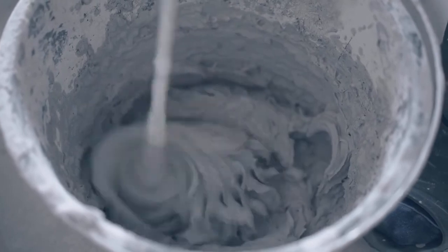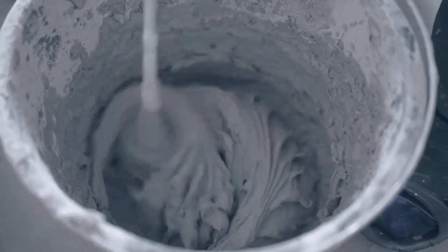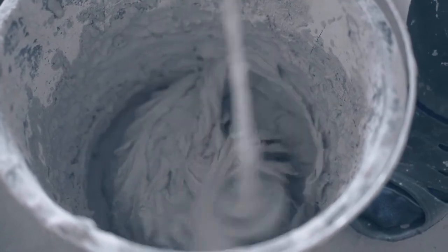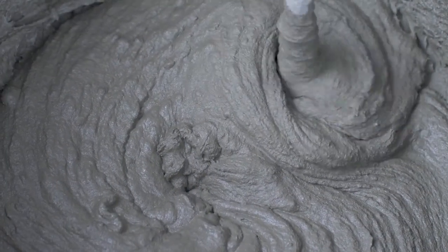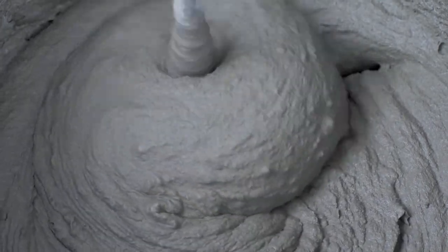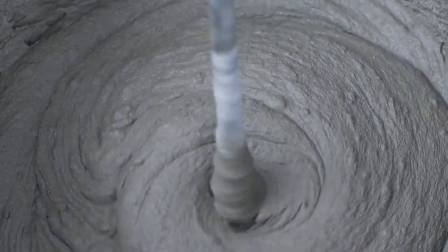So before that you need to use that one. Then you need to make use of a mechanical stirrer to avoid lumps. Now it's very important, because we cannot mix it by hand or anything else. You need to use a mechanical mixer to stir and mix it properly, otherwise lumps will be there. And let the mix rest for 5 to 10 minutes and then start the application. Now mixing is done.